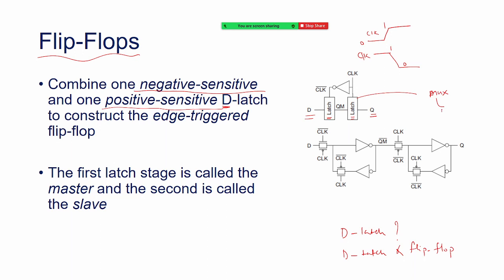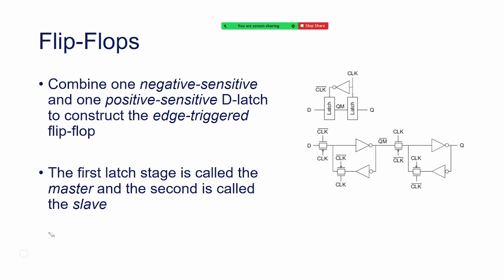Now again, coming to the question of Sangeeta, a latch is implemented by a MUX, and a MUX is implemented by pass gates, and a pass gate is implemented by compound transistors, pull up and pull down network. Pass gate, we know how we implement it: A and B, and this is G, this is GB. Are you following me? We'll see that circuit implementation. Do you agree with me? We'll see how the circuit takes place.